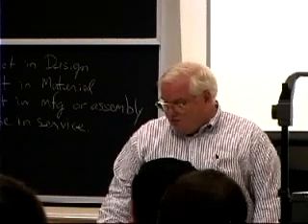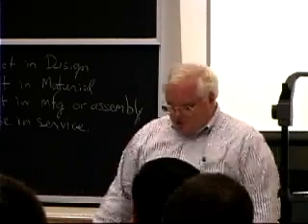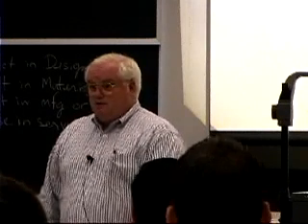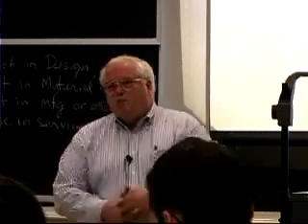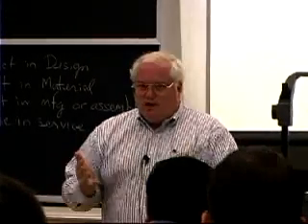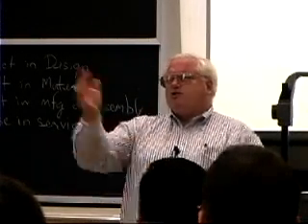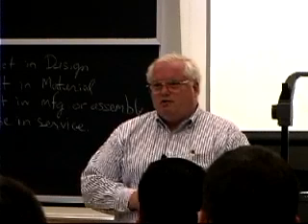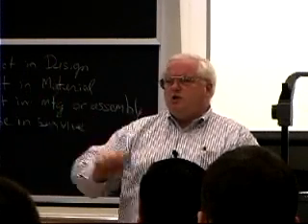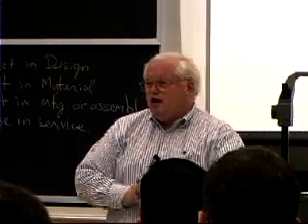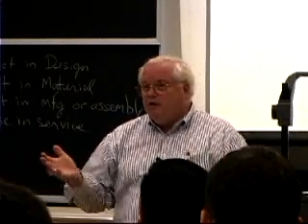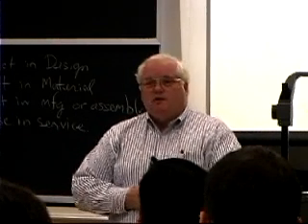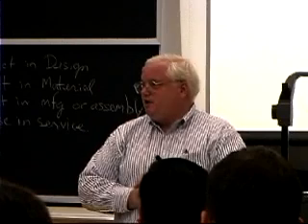By the same token, you find some people say, oh, it's a stress concentration, and you go and you look in the book and say, no, it's not a sharp enough radius. I mean, you can quantify it, is the point. Most people are not quantifying things. They just say, oh, there's a stress concentration there, that's why it failed. Oh, I saw an inclusion there, it was half the thickness of a human hair, and that was what caused it. No, excuse me, no. Not unless it's a piece of glass or a piece of ceramic, okay, that's very, very brittle.